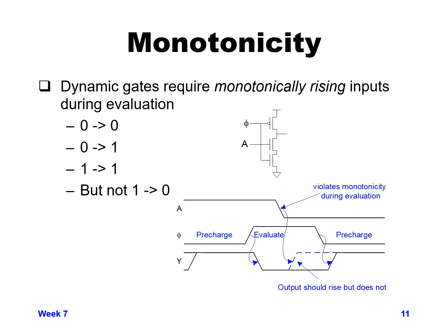And so your output goes low, and if your value of A really should be 0 and it came in late, so after the clock went into evaluate, A came in and switched from 1 to 0, you want the output, if this was a regular static gate, to go back high. But because the output only goes high when clock is low, the output can't recover.